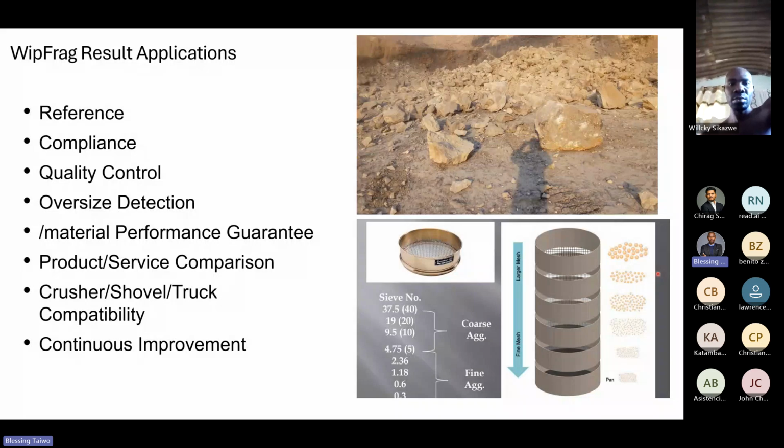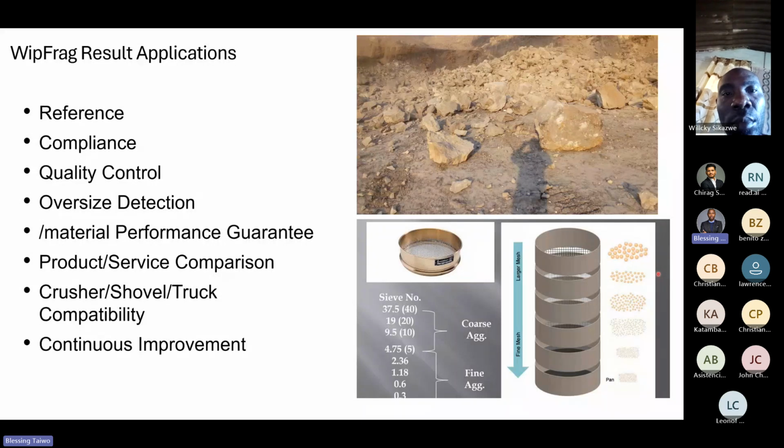It could be you want to compare 2 explosives, or you want to compare 2 detonation techniques. Maybe you want to compare electric detonator with non-electric detonator, or using ANFO with your explosive as secondary explosive in that charge at the column step, or you want to incorporate another type of explosive. These are some of the reasons why you want to assess the performance of that blast, to compare product